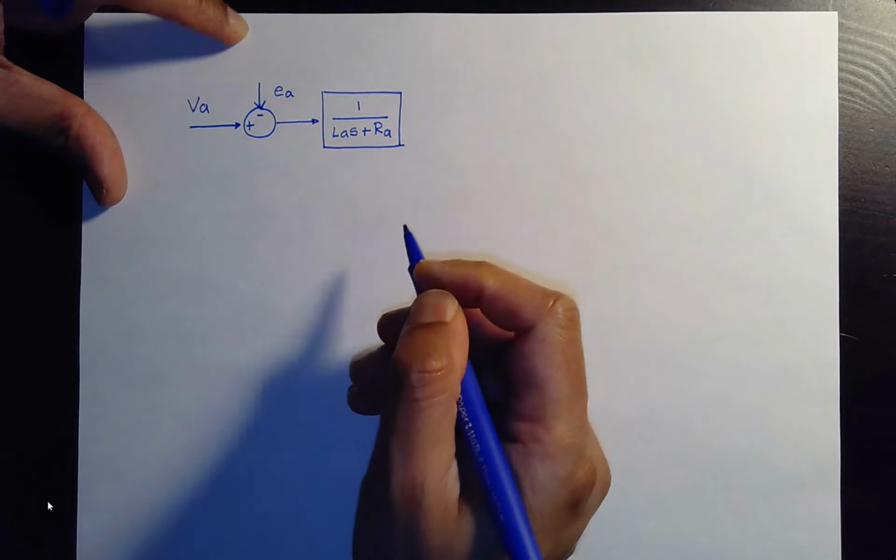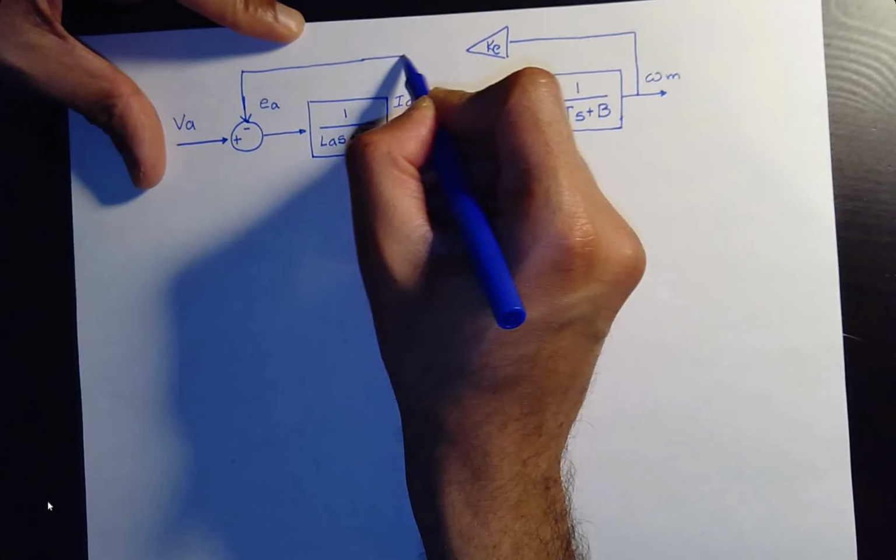We have the speed that we're going to control by controlling the voltage, and load torque is out of our control. We do have to make the final connection here, which is EA. It's Ke times omega m. This is the back EMF term, and we're going to sketch this right here. This is Ke, and we know that value already because we know Kt.